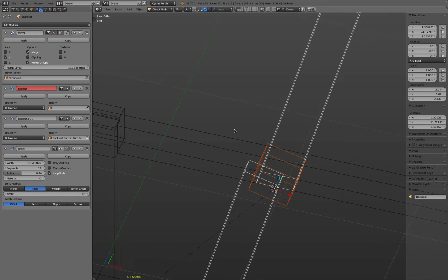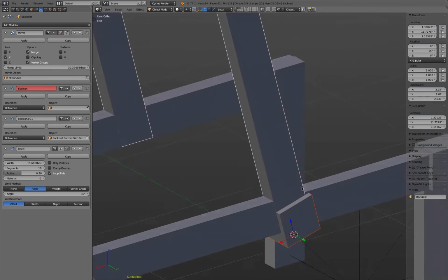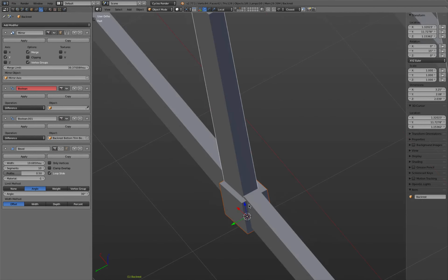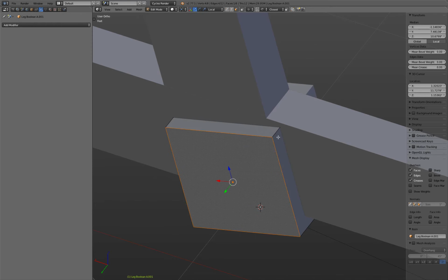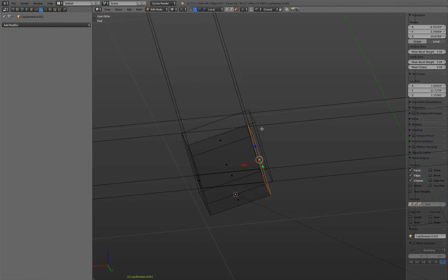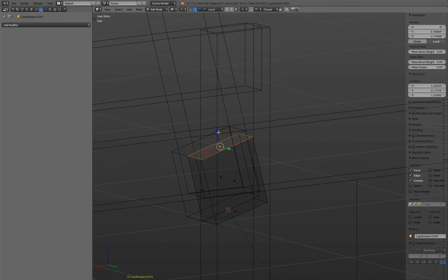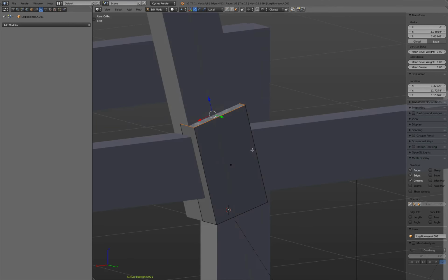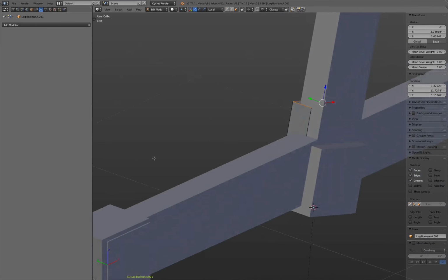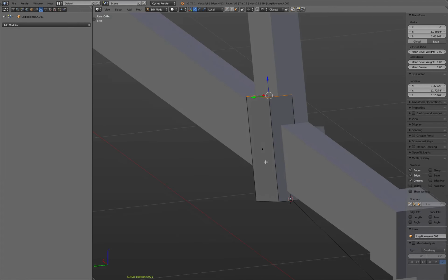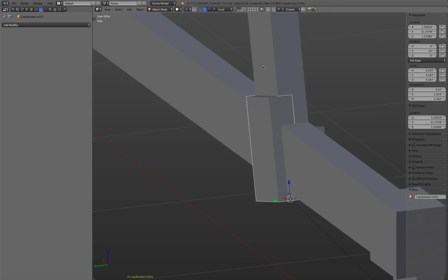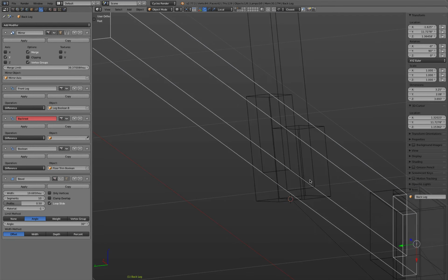So at least now they're perfectly positioned, so that is actually good, and we have to adjust the size a little bit. So for example, this face is way too big, so maybe snap to this one. Okay, and here for example move this one up. Great. So now we can use this, for example, to cut a space out of this plank.